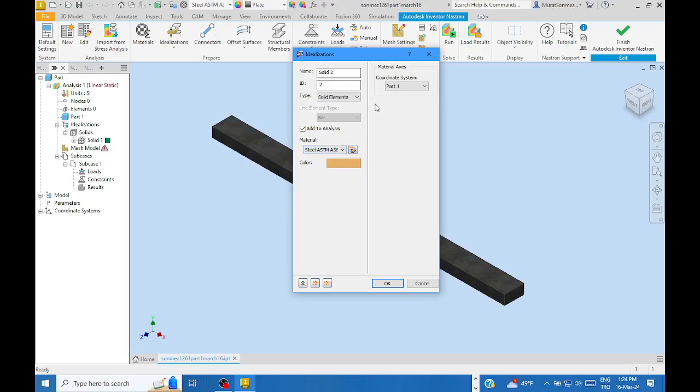That is good. But here, have this dialog box on the screen to teach the software whether the object is a solid element or a shell. Because accordingly, Nastran uses a different set of equations. Shell means a thin-walled object. For instance, the object is a pressurized vessel to store oxygen or nitrogen, or it is the shell of a boiler or steam generator. Pressure is in the order of many megapascals. It is a shell. So define that the object is a shell. Here it is not a shell, it is a solid element.